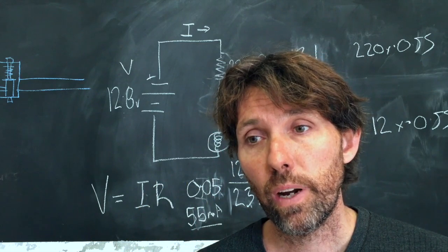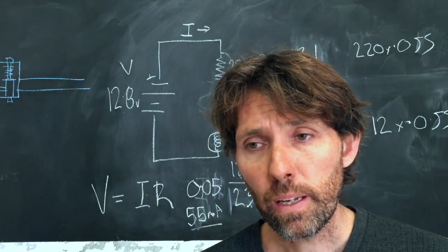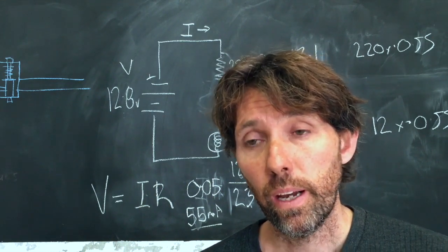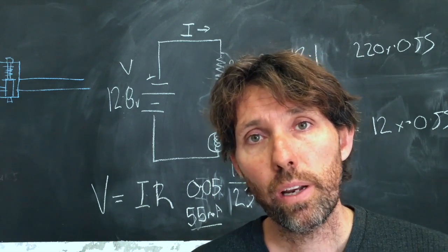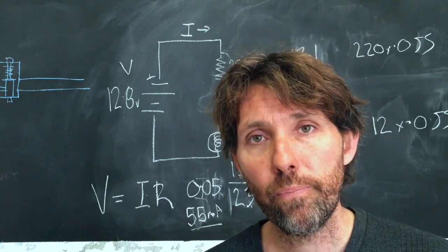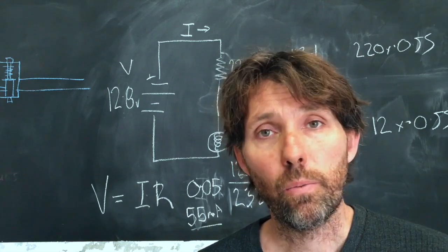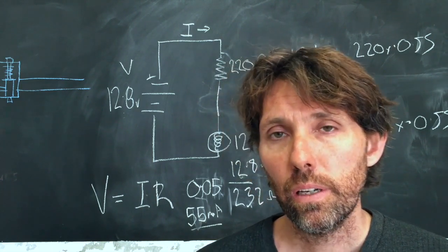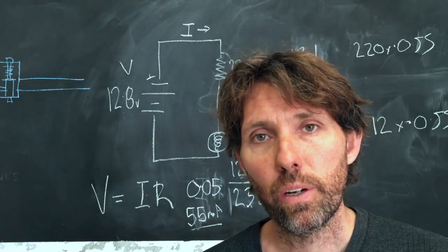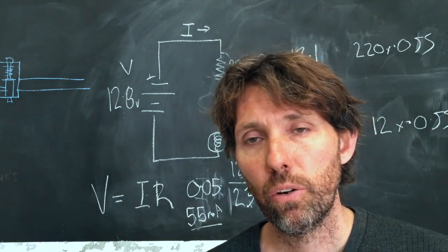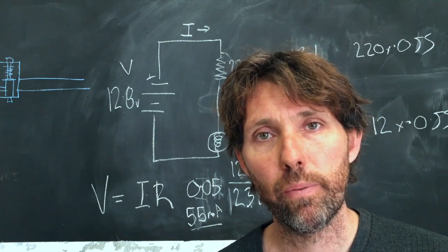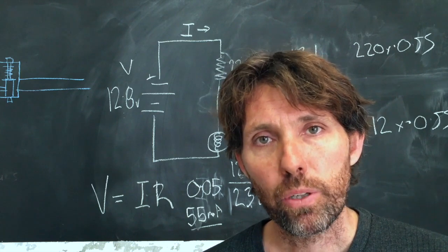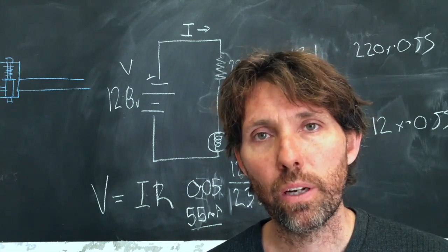Don't be afraid to just start doing your own wiring. In this case, it was the one wire that carries the power that was broken, and I had the same problem in my boat. So just run a separate power lead, just a single core wire. You're going to spend $10 on wire instead of buying another $200 loom. So I think once you get your confidence up with this, you realise that, no, I don't need to go and buy a many $100 Yamaha loom. I can actually just run a separate power lead from the motor, the same point that loom wire picked up, run to the front, problem solved. You've now just decommissioned that one wire inside the loom and you're all good to go.